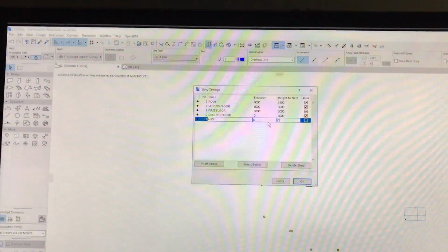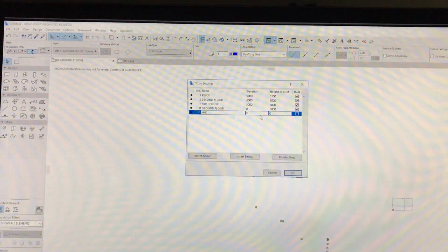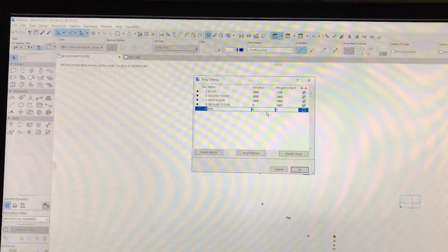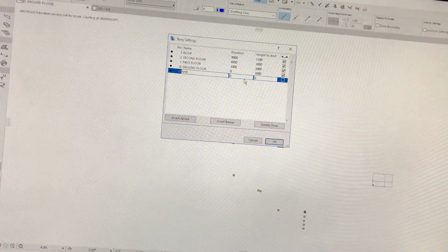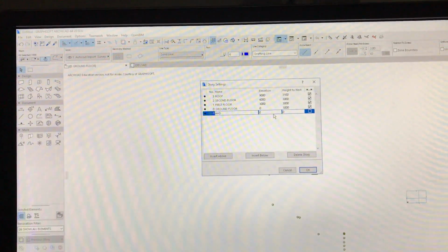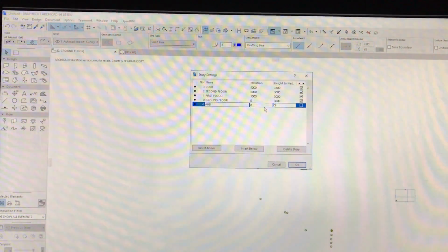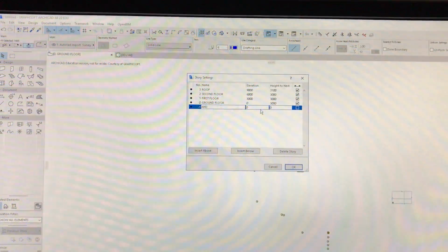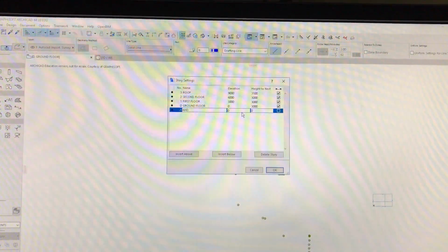I prefer, when I get a survey, to actually put it onto the AHD story. And then I turn on the trace so that when we're on the ground floor, we look through at our survey, we've got nothing drawn on the ground floor so far. As we need to get elements from the survey, we can either go downstairs, copy them, paste them up to there, or we can draw over the top and create everything in 3D after that point.